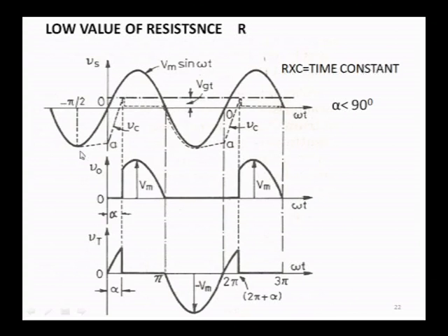You see the capacitor here. So, this capacitor voltage will come and stay somewhere here, OA. This is the voltage of the capacitor. It reduces to some extent. When the input voltage crosses this junction 0, observe the capacitor, it has started discharging. This is the line of discharge. So, it discharges. When this discharge voltage is equal to Vt, then only your SCR will trigger.